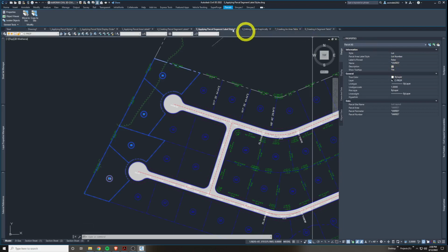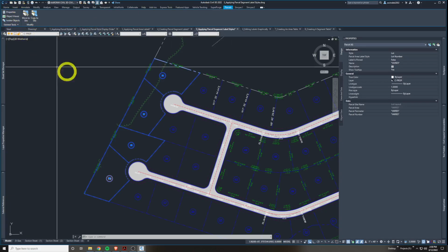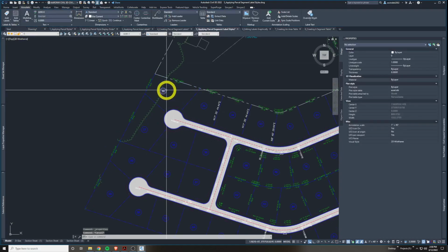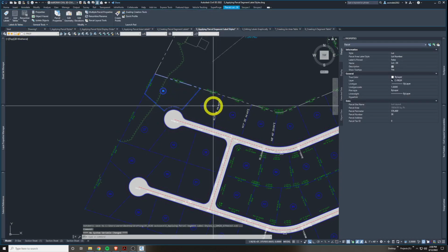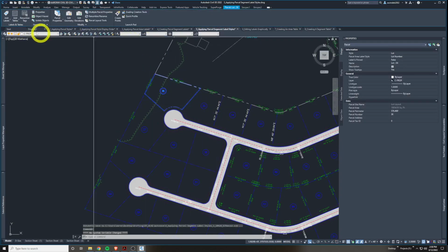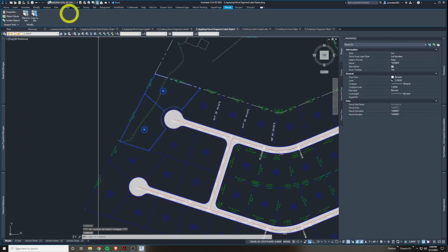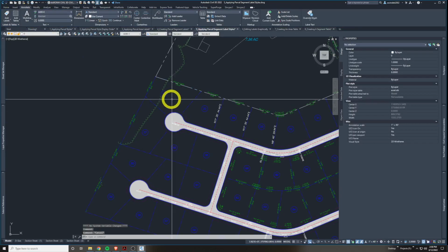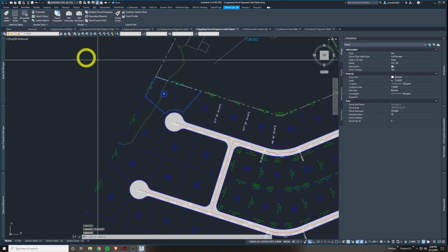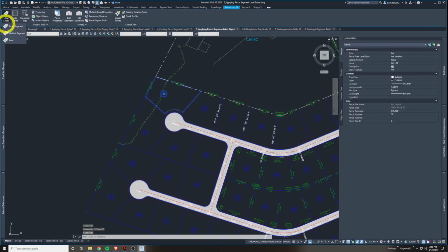I'm not actually seeing what it's describing. I don't have label options when I have these multiple parcels selected. So I can isolate them, get properties, go to different sites, but I almost have to do one at a time. So let me pick 1. Now I should have the option to add labels. Yeah, I do. If I pick 2, that goes away in my contextual ribbon. So disregard that book instruction. Pick 1, say add labels.